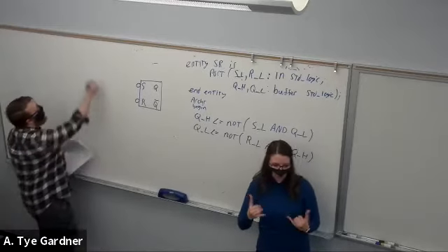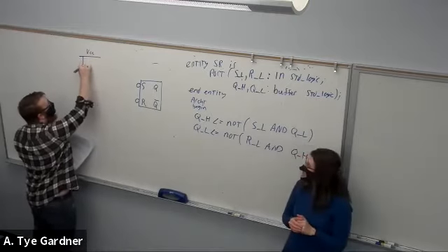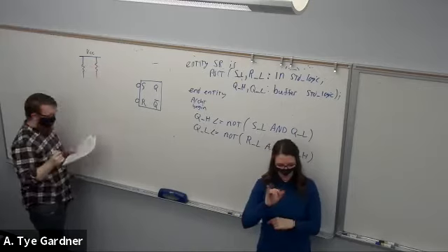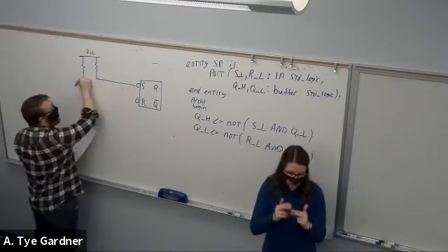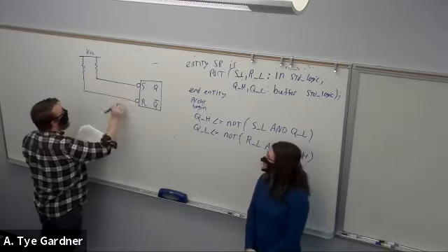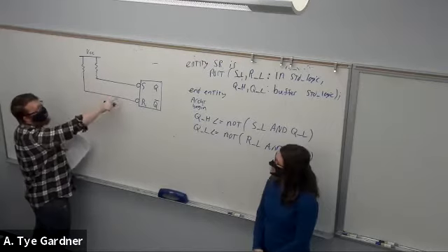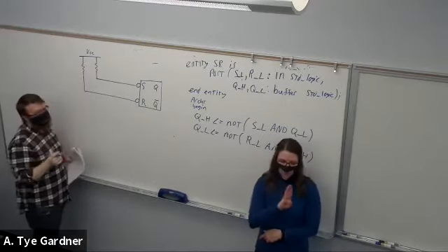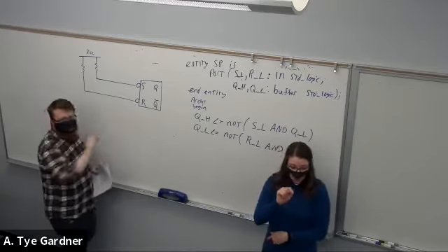Now, let's build one of your guys's, well, 2 switches, actually, that you've built many times now on your circuit boards. So here, they're getting pulled up to 1 by default, right? So their default state is 1, and since they're active low, that means they're both off.